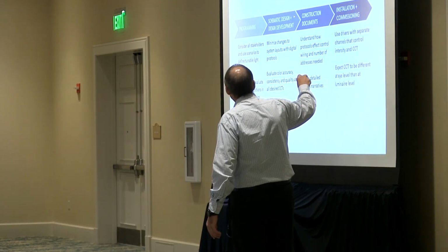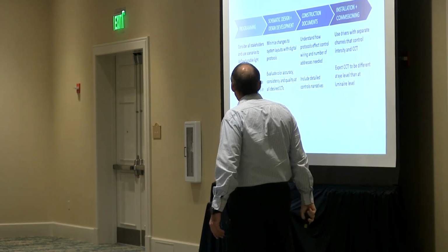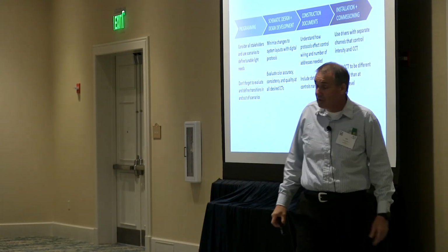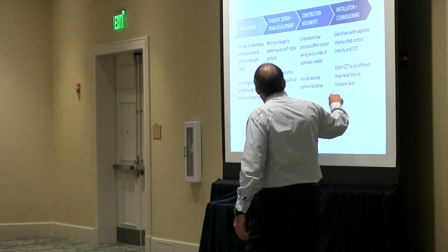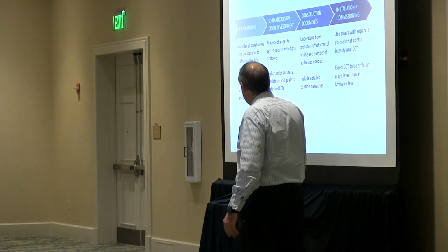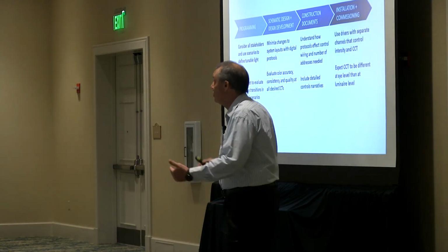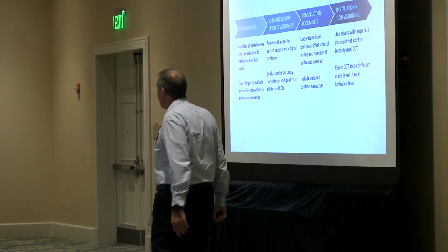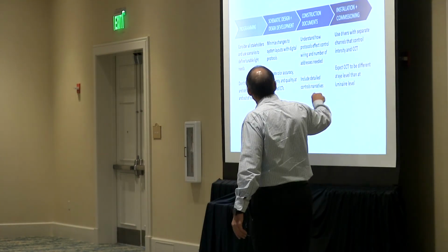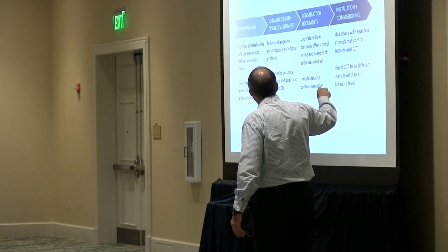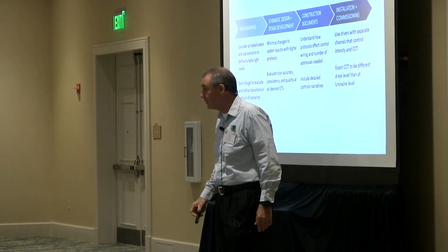And then when you get to schematic design, if you use this digital protocol, you're going to minimize changes in the system moving forward or during the design phase. And you really want to be evaluating the color accuracy, consistency, and quality of the fixtures. You want to sell me this fixture? You want this fixture on my job? Give me a sample. I want to see it. How does it work? Understand the different protocols and how they affect the control wiring, and then include detailed control narratives.